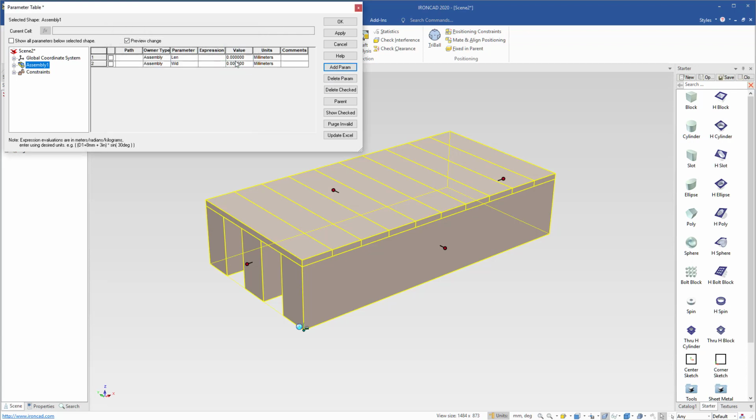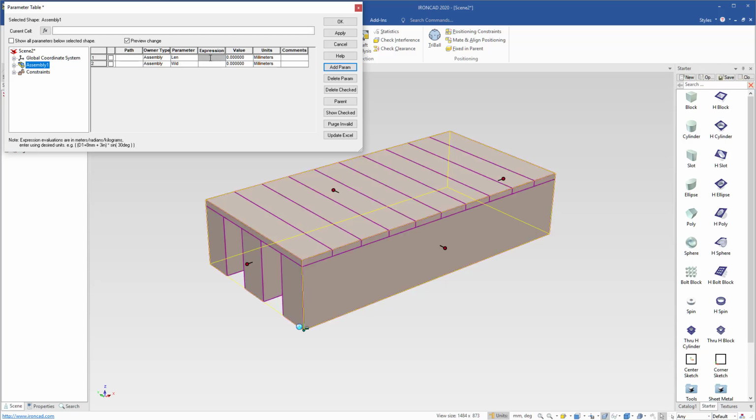So what we want to do is we don't want to use the parameter table to type in values to drive things. We want it to pull from the handles. And to do that it's a simple expression. It's basically saying grab your size box, and then which size box do you want? You put a slash there, and on this one we want the length handle, so we just type in length. If I spell that right, there we go. Type in length, and you'll see that it automatically pulled the current value for that. And we'll do the same thing for the width. Make sure I'm spelling right today, and there we go. And it pulled those values in. So those are basically automatically pulling the value of those handles.